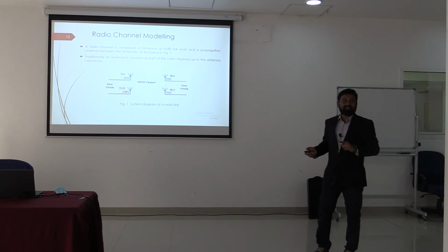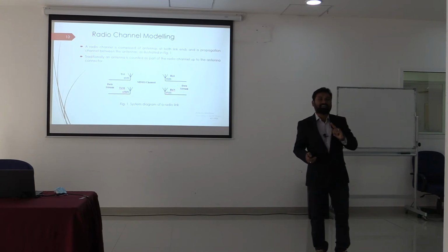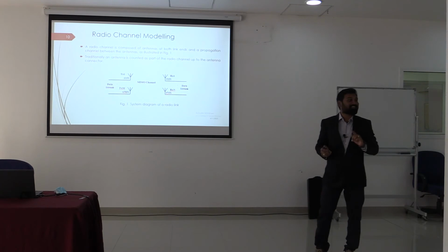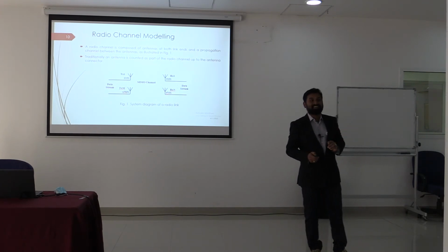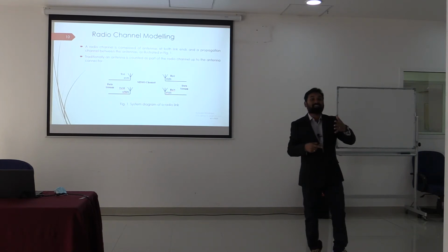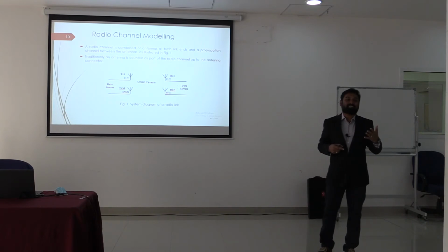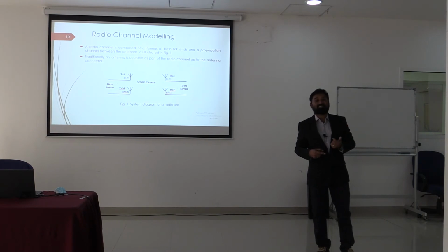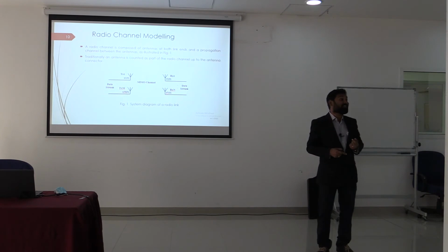What they state is, keep on increasing the number of transmitting and receiving antennas. If one channel goes deeply faded, the remaining channels do not get faded. This is not a new concept. We call it the rake receiver in CDMA. We know it is a fingering concept. You are transmitting channel 1, channel 2, channel 3, channel 4, channel 5. If one channel goes deep faded, the remaining or the closest channel will not get deep faded. That is the probability of error or probability of channel ergodic capacity, which was calculated 10, 15 or 20 years back, which we call the rake receiver. That is the concept used in CDMA phones.